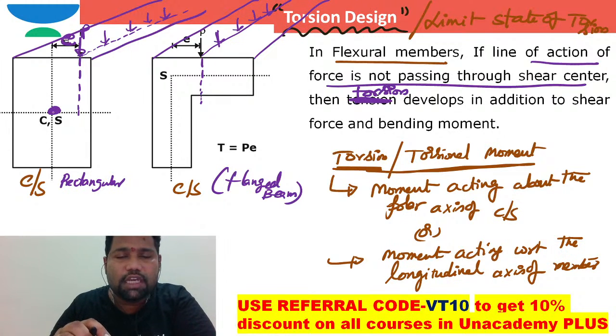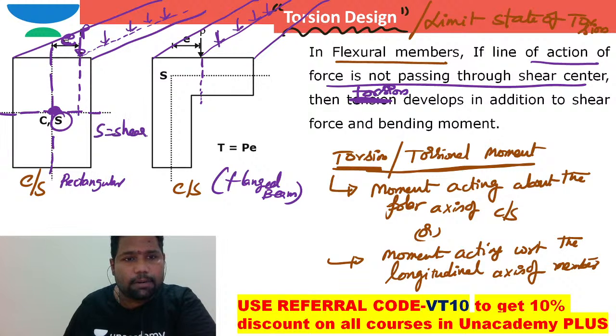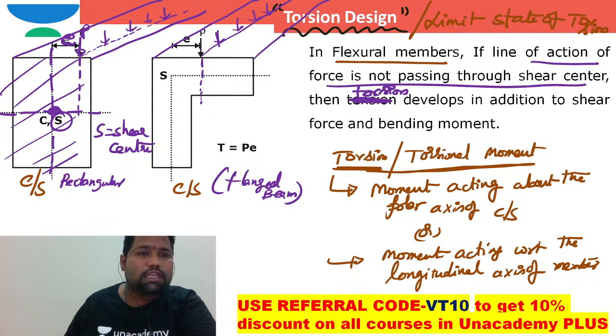Where you learnt about the shear center, brother, is in your strength of materials. Your teacher might have taught you how to locate the shear center for different cross sections, right? Especially when it is a symmetrical cross section, the shear center coincides with the centroid. So here this is the centroid of the cross section. Here, SC stands for shear center. The shear center coincides with the centroid because this is a symmetrical section. I hope you are able to see. Now this is the shear center.